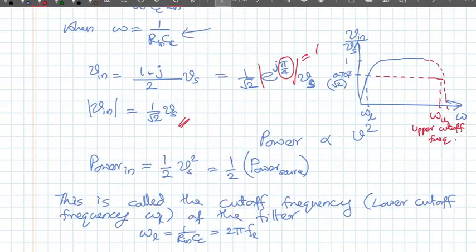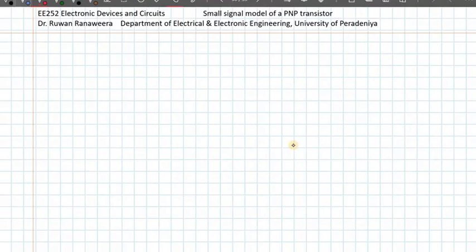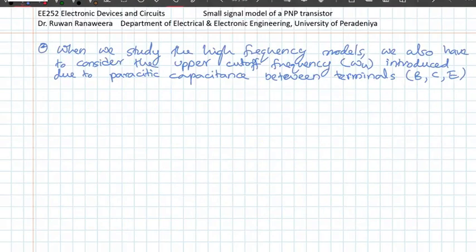Okay, so let me give you that also as a note. This parasitic capacitance is not any particular capacitor that we have inserted, but inherent capacitance that exists because there are two terminals, and between any two terminals you can have a small, unintended, unwanted capacitance. Those values are very small, like picofarads, or tens or hundreds of picofarads, but at high frequencies they become significant.